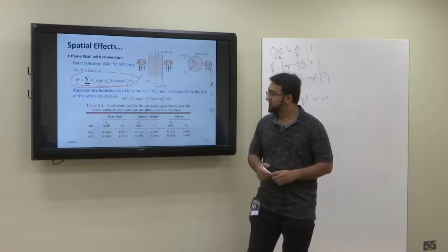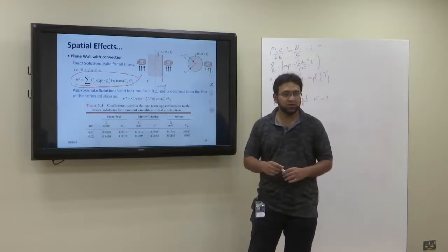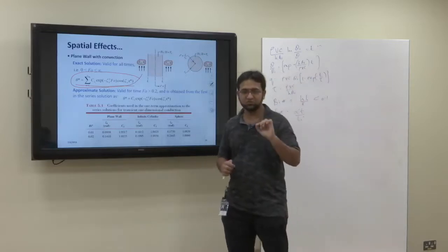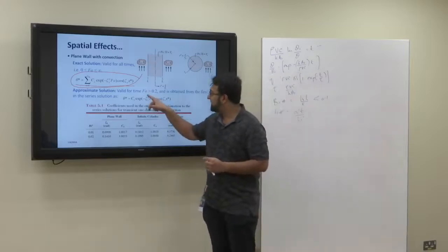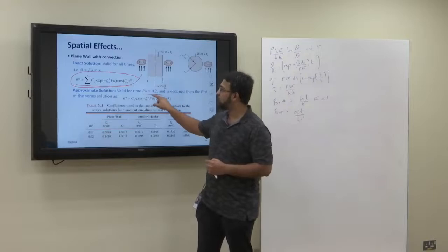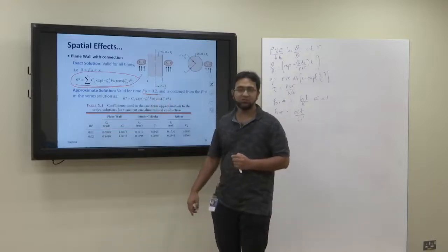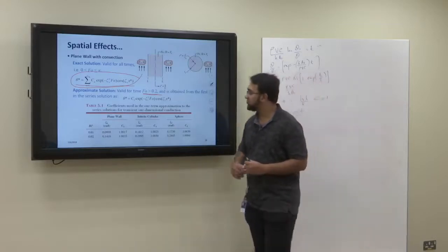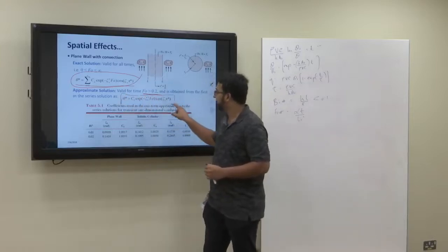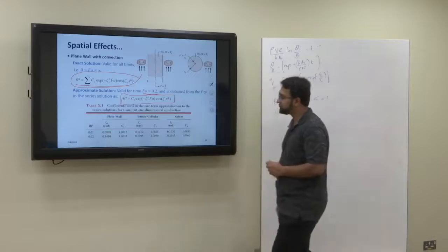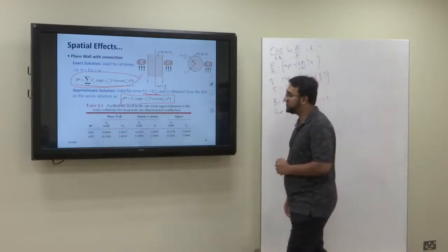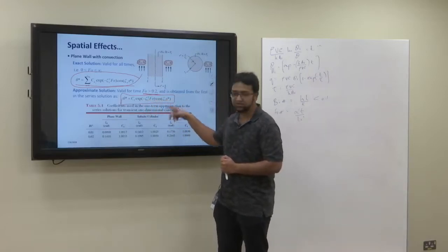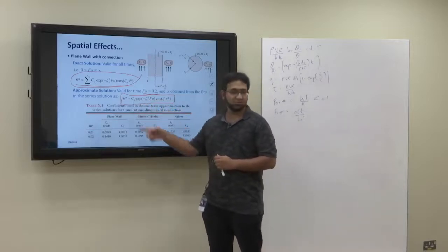Now the thing is that we can solve only for the first approximation if we apply only the first approximation. So first approximation constants we have to apply, and then it will be valid only for a limited range of Fourier number. If the Fourier number is greater than 0.2, then first order approximation is applicable. And if the Fourier number is greater than 2, then this becomes the solution: theta star equals C1 exponential of negative eta 1 squared Fourier number, into cos eta 1 x star, where eta 1 and C1 are the constants here.